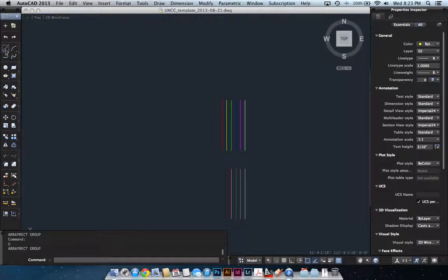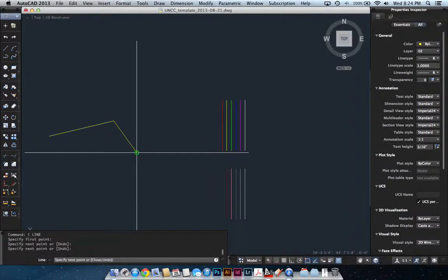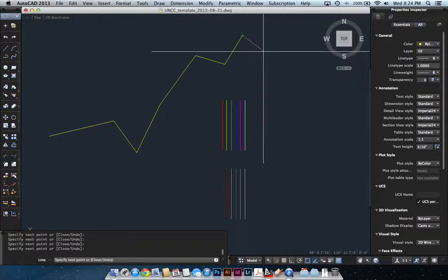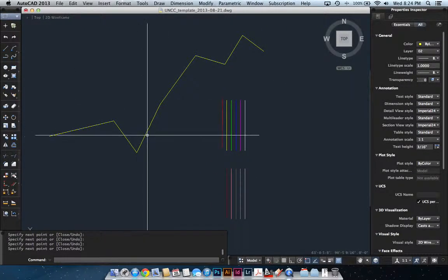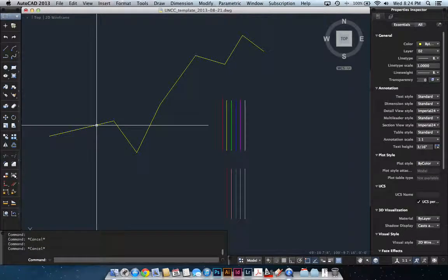First thing we're going to go over is the line versus polyline scenario. That's actually something that's come up a few times in class, and I figured I'd go over it one more time. You can always grab those from the menus over here, or you can type in line or polyline to get at the command. So I'm going to draw a line, and with a line I can continue running by left clicking and creating any sort of shape I want, following any path I want, and then hitting enter or a right click to terminate that. Except with line, I now have this as separate segments, even though I continuously drew it.